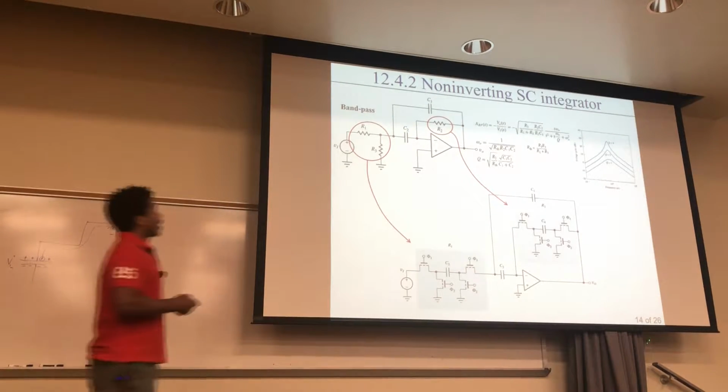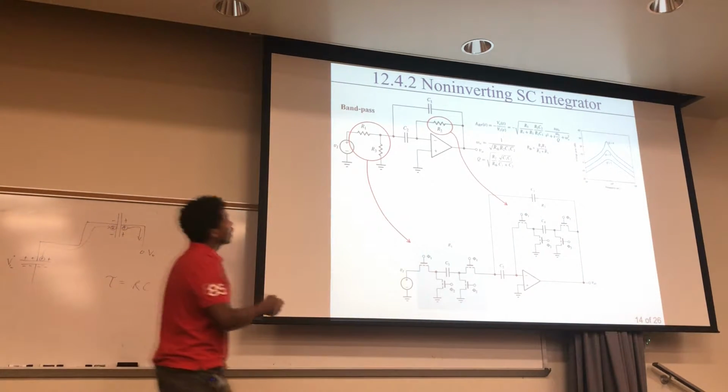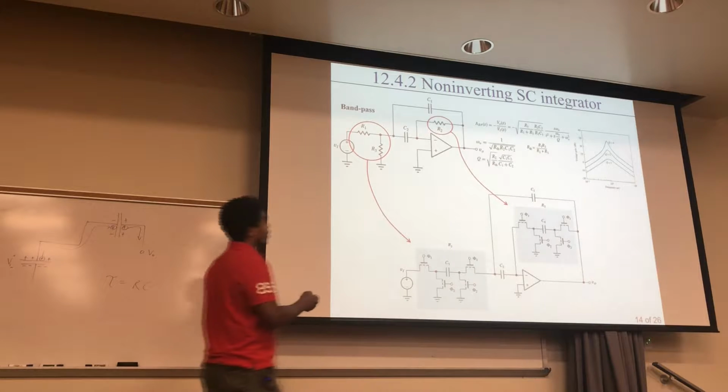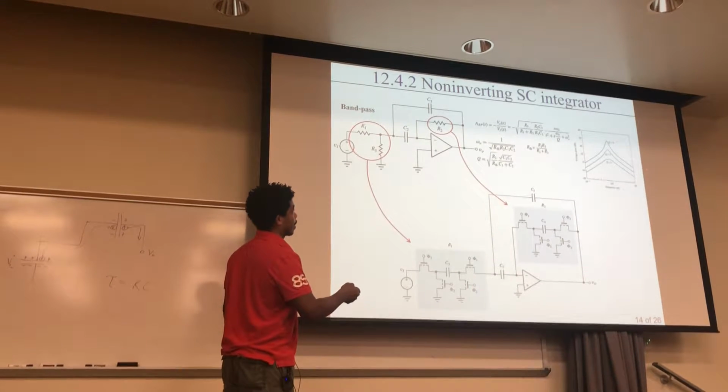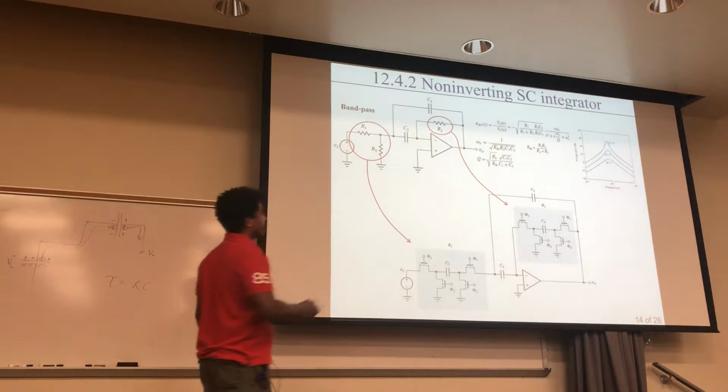Okay, and we're going to place the Thevenin equivalent right here with this piece. And remember what these were. Here's the amplitude as a function of frequency. Here's the cutoff frequency in terms of the R's and the C's. Here's the quality factor in terms of the R's and C's. And here's what the band pass looks like at different, like a family of Q's.